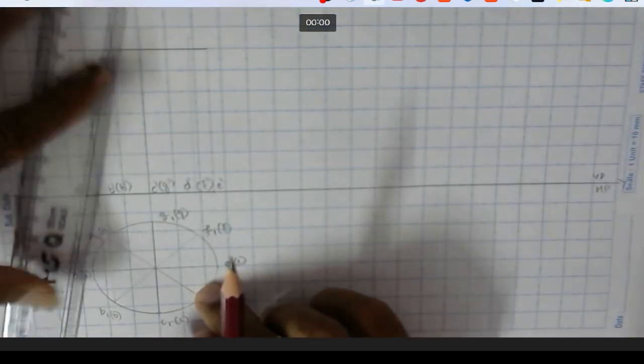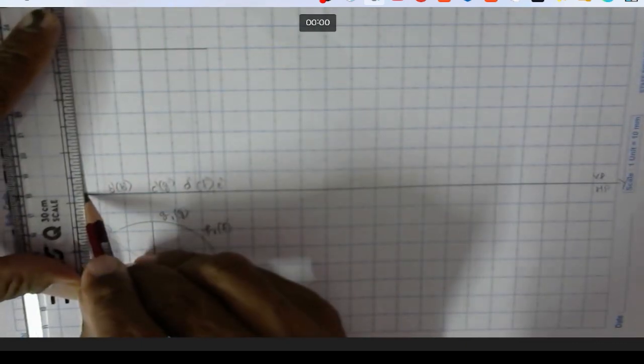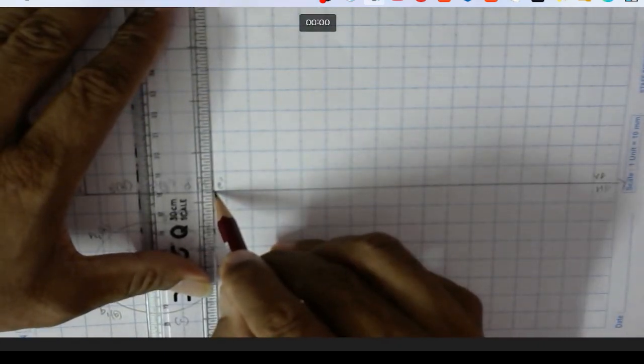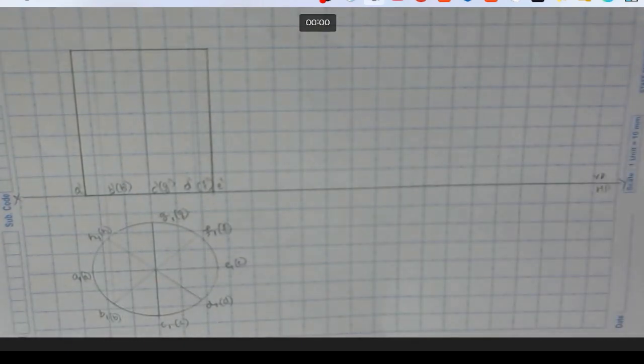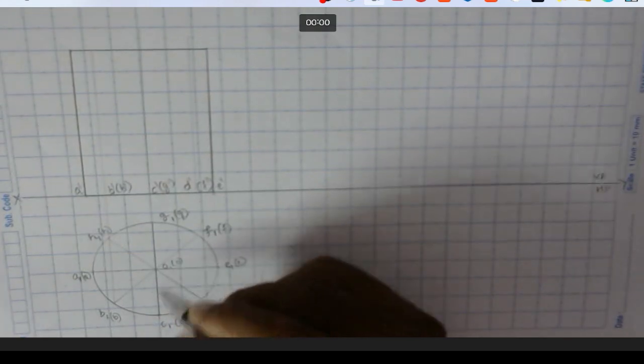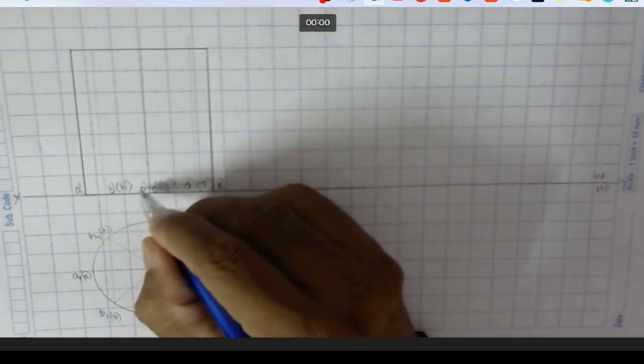So as you draw the generators, for the extreme outer generators you make them thicker, because when you look at a cylinder in the perpendicular direction, it is going to be observed like a rectangle. Okay. Now we can mark the axis also. Let us go for O1, O here. So here I got O dash.